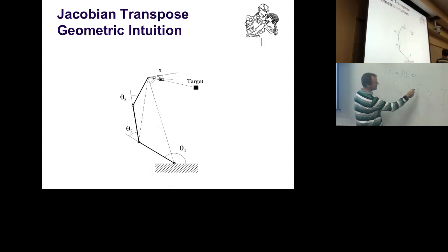In each of the original columns, we have a 6-vector which shows us in which direction essentially the thing can move based on that joint angle. How would the end effector position change, and how would the end effector orientation change? And you have this interesting little 6-vector sitting here everywhere. And now we're multiplying this with this interesting little delta x vector. It means you are now asking, and delta x has first 3 components for position in the direction you want to go, and 3 components for orientation you want to go. So now we're projecting essentially this delta x vector with an inner product onto the effective motion which that degree of freedom can contribute.